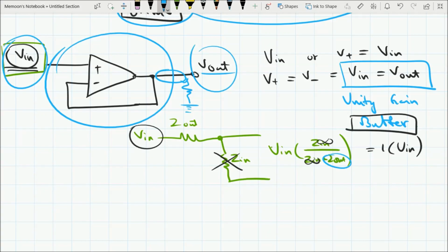So this was the most basic feedback circuit for an operational amplifier, in which we reduced the gain from whatever value it was to 1 and made a unity gain buffer, and we saw that rule number 5, where the op amp changes its V out so that both the inputs are equal, is actually implemented.